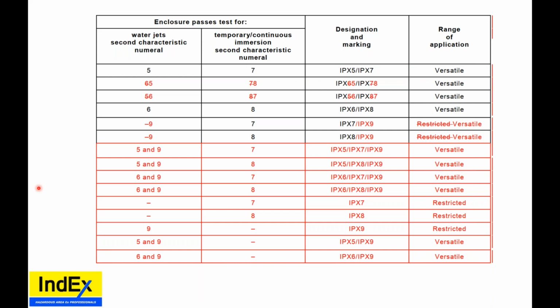That is for the manufacturer and EPC to decide, and the end user. But if I were to have a facility, depending on the area, I would call minimum IP66. But in industry, usually we have instruments at IP65, electrical at 66, motors at 55, but rarely do we only accept IP54 outside. Now, glanding, that'll be next week's subject.